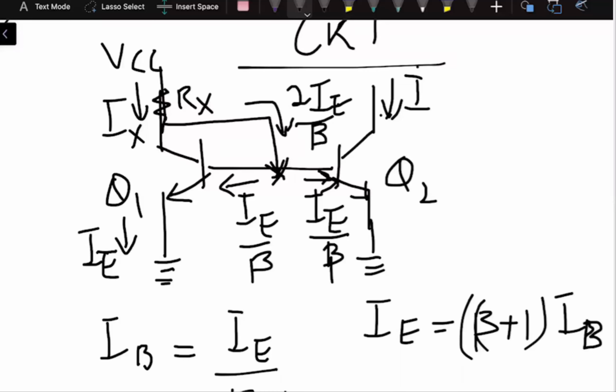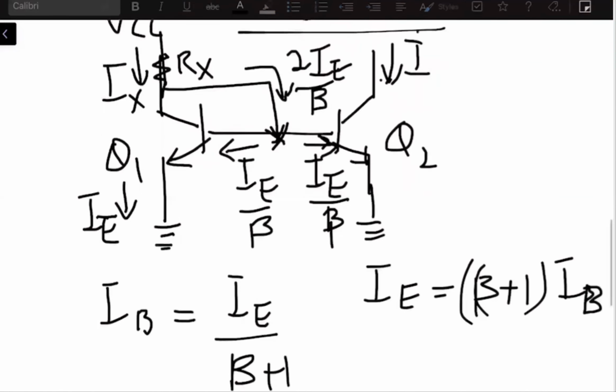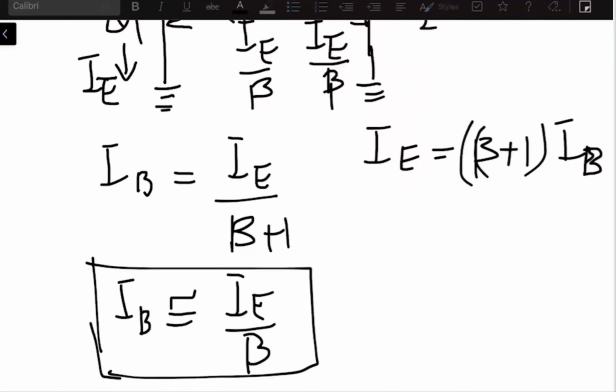Say that there are two transistors Q1 and Q2, right? And both transistors are being manufactured on the same chip, so they have identical properties. Once they have identical properties, as they are connected to one another, if the base current flowing in Q1 is IB, then the base current flowing in Q2 will also be IB, right? And what we have said over here is that IB is actually equal to IE by beta, right? Are you with me?